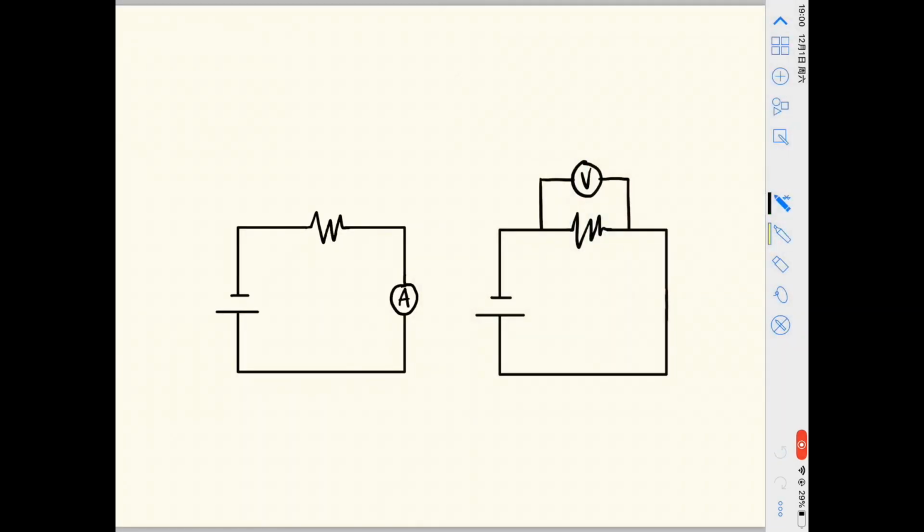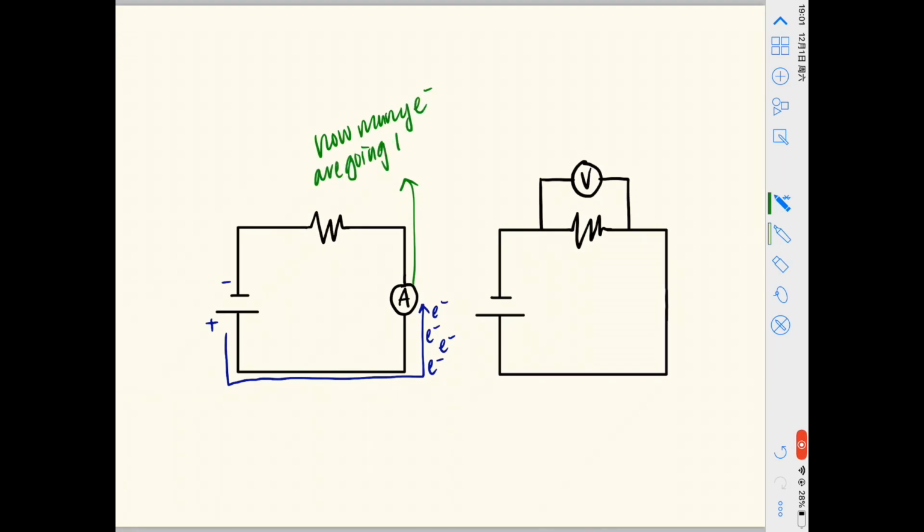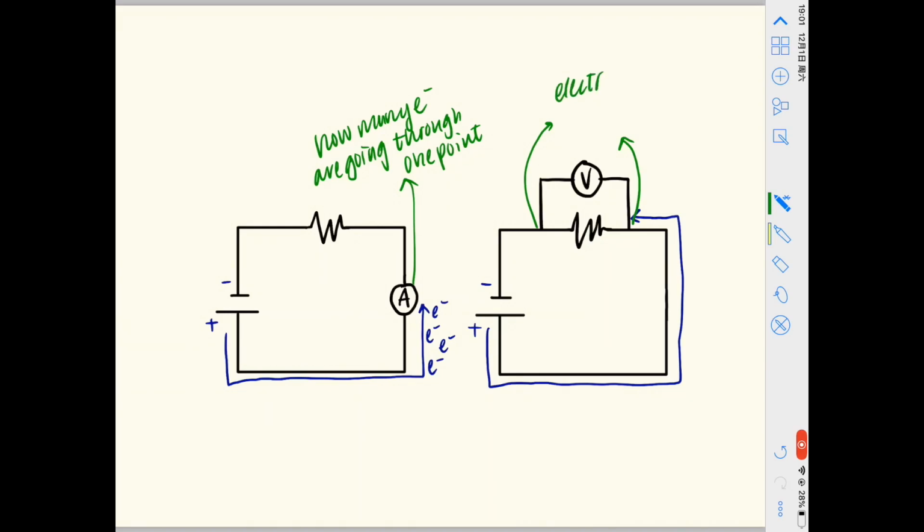So what are voltage and current? We can think of voltage as the work needed per unit charge, or as the electronic potential difference between 2 points on a circuit. We can use the unit of volts for voltage. Current is the amount of charged stuff flowing through a circuit at any given time. We use the SI unit amperes to describe current, which is the flow of electric charge across a surface of 1 coulomb per second. So how does this help us define resistance? Since resistance is the ratio between the electronic potential difference and the charge moving through a circuit, we can describe it as the measure of an object's opposition to the flow of current.